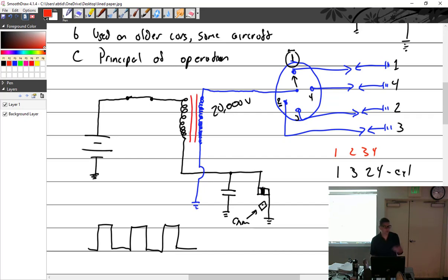That's why during the oral, I always ask you, which direction does your magneto rotate? And I'm surprised how few of you know that. That's okay. And then I turn it around and say, well, which way does the distributor go? Because that's this part back here. I say, well, if this is a left-hand rotating magneto, that means it turns to the left when you're looking at it from the drive end. So it turns to the left. Then I turn it around and I say, then which way does this go? To the left. It just goes to the left too.